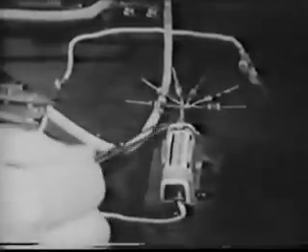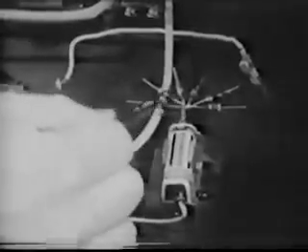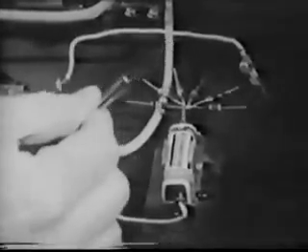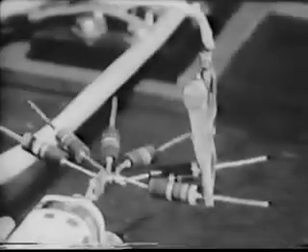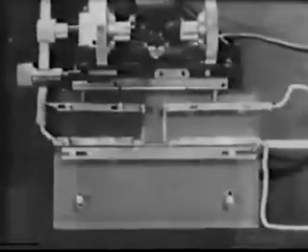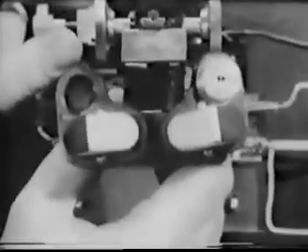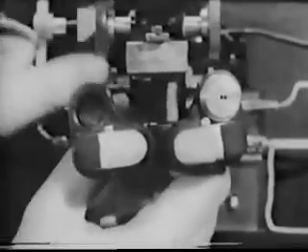The lead from the negative terminal is connected through a resistor to this brass strip, which holds the detector point. The resistor is chosen for best signal-to-noise ratio. This probe will be connected to the vertical input of the oscilloscope to monitor our detector current, and this is the ground. Now we're ready to focus the light on our bar using the right half of this binocular microscope